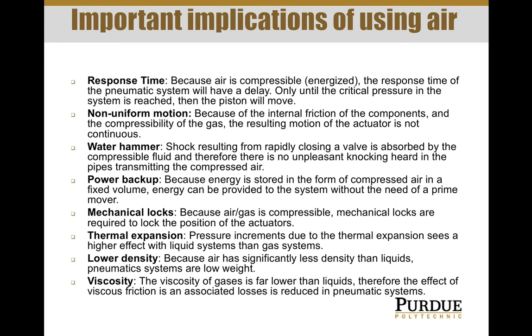Now, on the bright side, compressed air systems, or pneumatic systems, don't see water hammer. Water hammer is the shock, the audible noise that liquid systems produce when a valve is suddenly closed, and you hear that knocking on the tubes. You don't see that in pneumatic systems because of compressibility. There is that give, and then all that energy is absorbed by the compressed air.